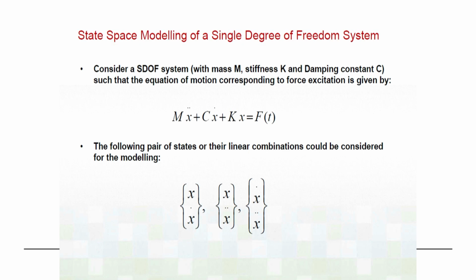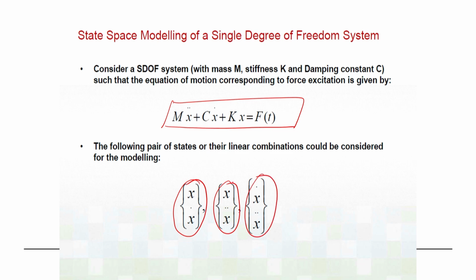Now, the state space modeling, through this tracking, will also give us a governing equation of motion, just like we have obtained in the other case. The only point here is that for state space representation, we will be happy to keep the relationship in the time domain, whereas in the other case we represent it generally in the frequency domain. Now, once I get this equation of motion, I know what my states are, like in this case two states are required. So, I can choose between position and velocity, or position and acceleration, or velocity and acceleration, any two. That is my minimum set.